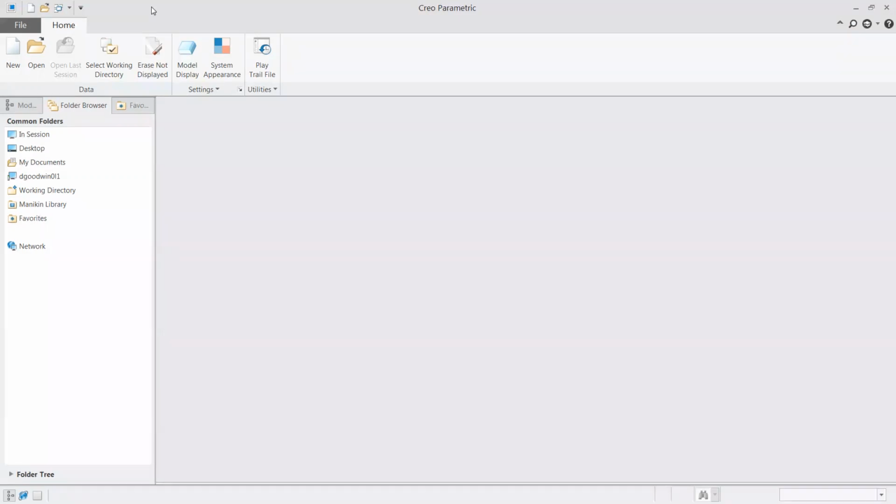So again, if any of those surfaces change or anything was deleted that those annotations were tied to, it understands that, it's able to update. And if a surface is now gone, it'll throw you a warning, saying, hey, what you were referencing before is now gone or changed. What would you like to do, right? So the change anywhere is reflected everywhere. Yes, exactly. If you have something change in the model, it's probably something that you want to see or be aware of at the very least. So that's definitely something that has played into that process.